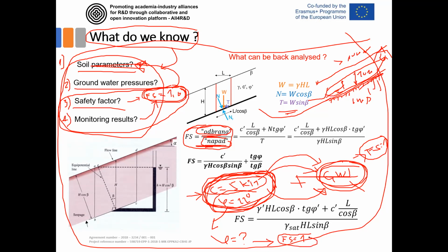And what we also must be sure of is that after remediation, after drainages, retaining walls, anchored walls, and so on, we need to bring this safety factor from 1 to some value over 1.3 or 1.25, depending on the code, the standard that we are using.